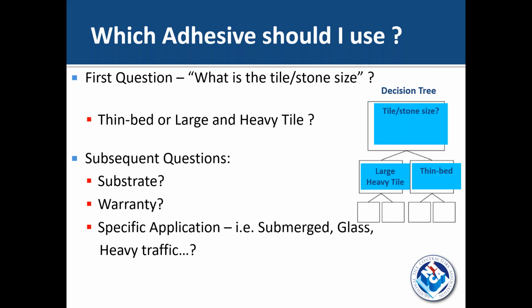So a movement joint is to give you room for the growth and shrinkage of that substrate or the tile as opposed to each other. Yeah, I agree. There should be no thin set or grout in that joint. You do not want to fill a movement joint solid with grout or thin set, whether it's against a wall or a cut movement joint.